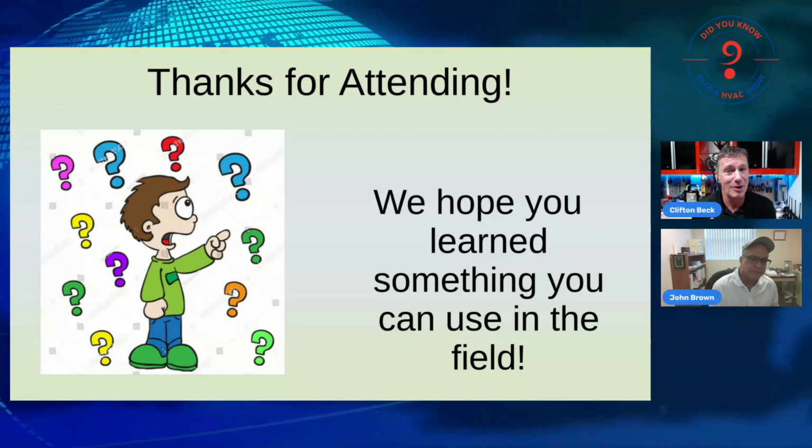You're way too generous. Now, before we go, I promised them a quick refresher on how to ohm out your circuits. You'd be surprised how many guys think this is a difficult thing to do. It's really not all that difficult. Now, granted, you've got to disconnect things and set up your meter and so forth. But even brand new cables that have been routed into a home can be compromised quite easily by staples, sharp edges on the duct, nails, and so forth. We all know this. We don't want to admit it, but it does happen.